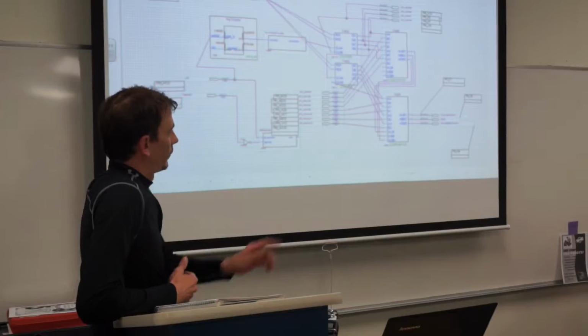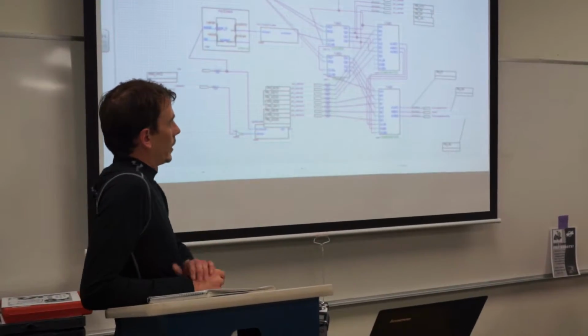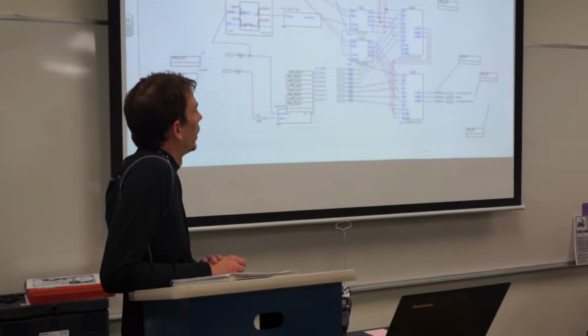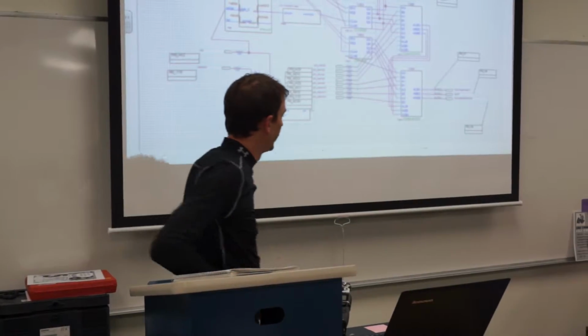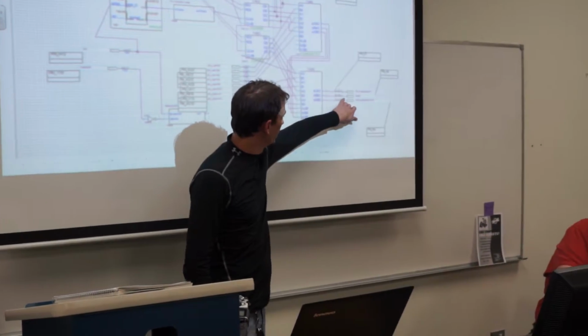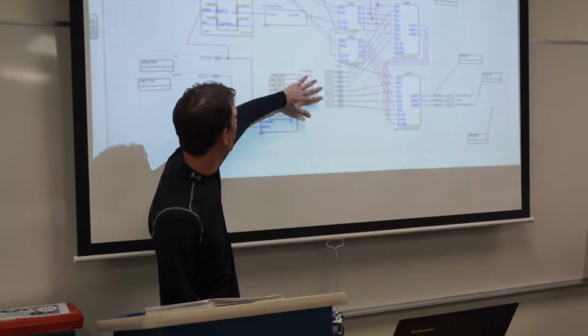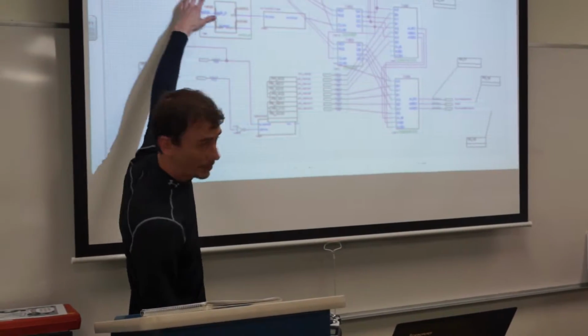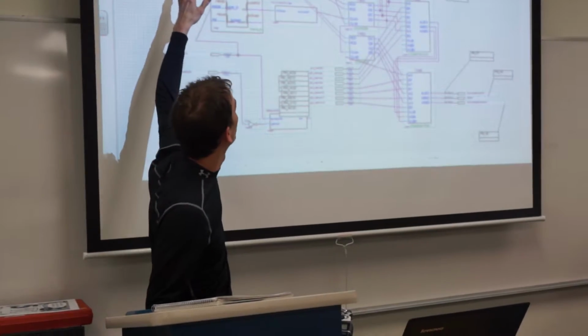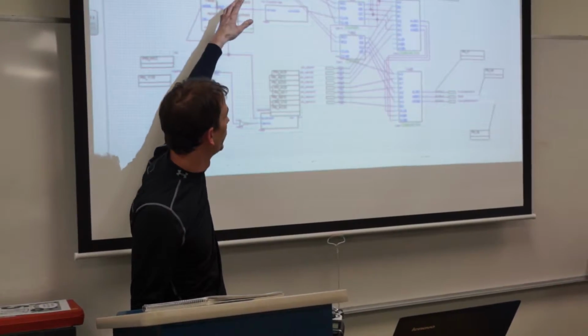4-bit counter. So I started off with just a 4-bit counter and then a 4-bit comparator. And I got that working to achieve our PWM output. That happens right here. These are the human inputs, scaled up to 8 bits. It's coming from the same 50 megahertz clock. We did divide it down.